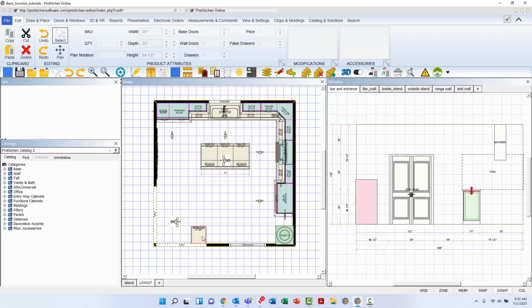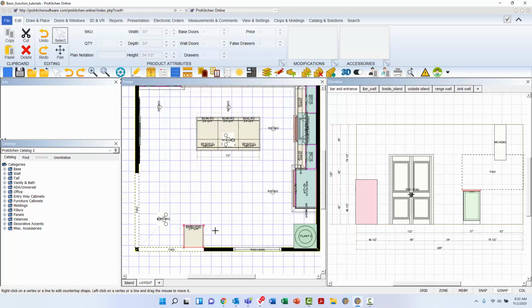The next right-click tool is the Edit tool, and can only be accessed and used in the Plan view. The Edit tool will assist you in making dimensional or shape changes to the selected countertop. Once selected, the mouse will become a crosshair again, denoting the Place Edit mode, and the countertop will be outlined in red and now have red open circles or points at each corner of the countertop.